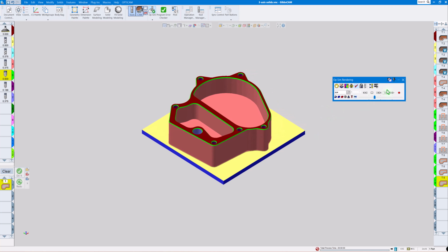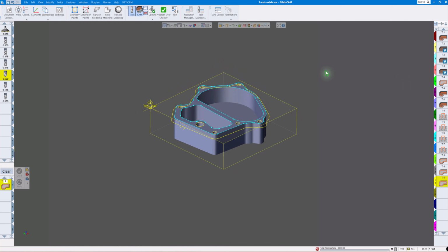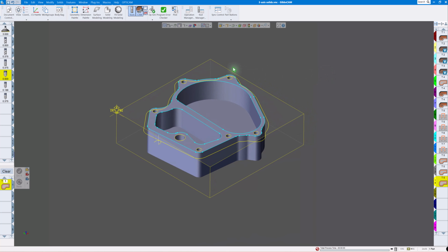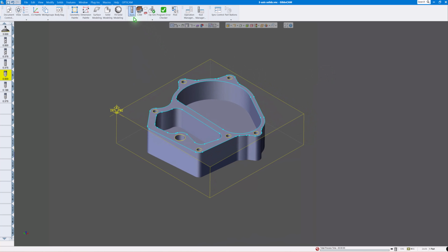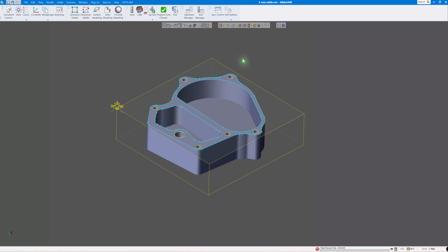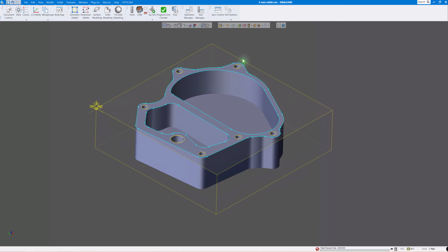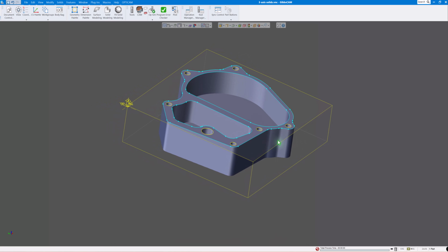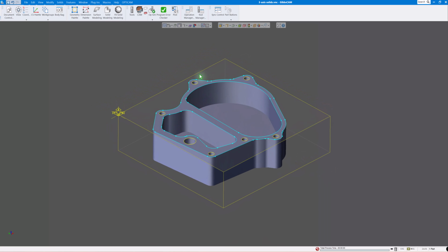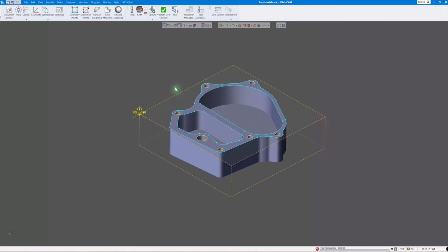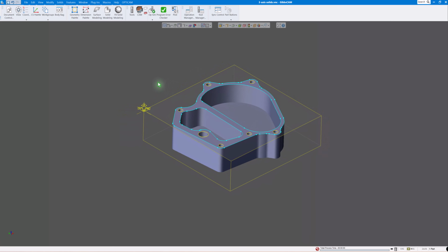Now we need to add the vise in, and this time, of course, we have a solid to work with, so that'll make bringing in the vise a little bit easier. But first I'm going to close the cam and the tools so we don't accidentally delete something. Now since I'm bringing in a vise, I want to kind of work with a solid. Now there's not a flat surface on here to bring the jaws up to, and like on class number 2, we just kind of estimated there. But this time we're going to bring in a solid and actually put it in the correct positions.